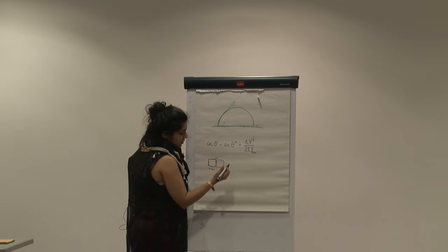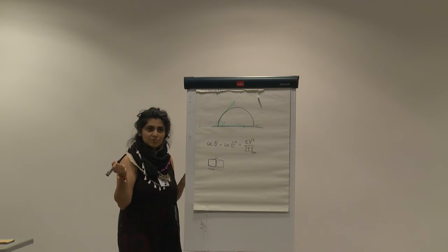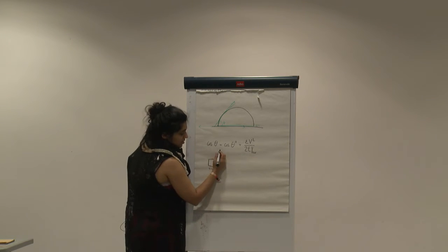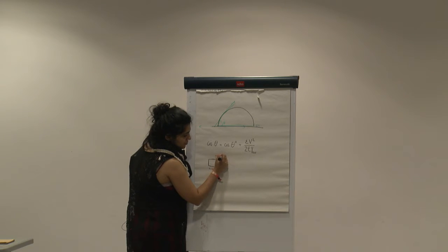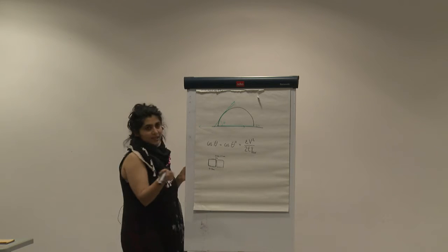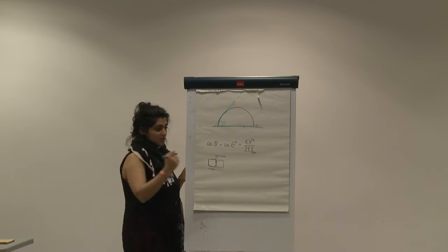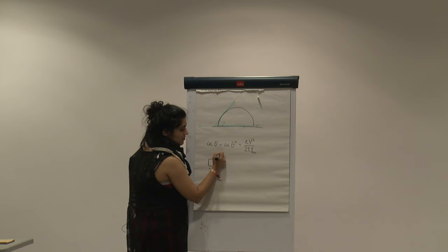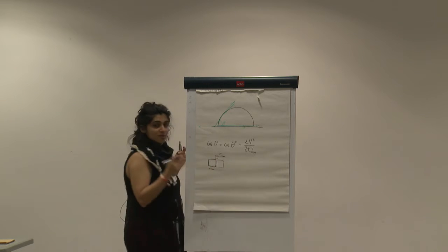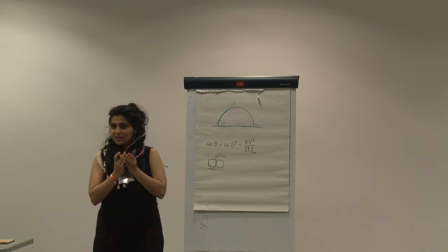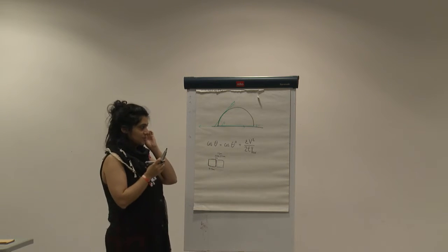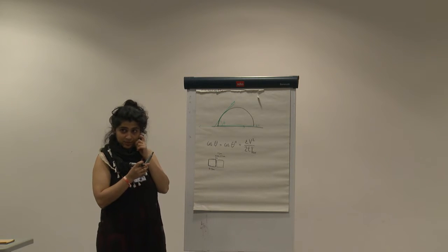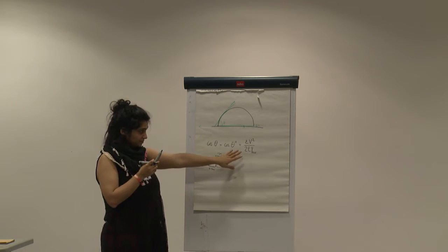And the gap, in our case, because we do PCB etching, is like 0.1 millimeter to 0.2. But if you do chromium deposition, it can be 1.5 micrometer. So they're very close to each other. If you have high voltage, the electrons can jump from one to another across the gap, and you can have sparks.